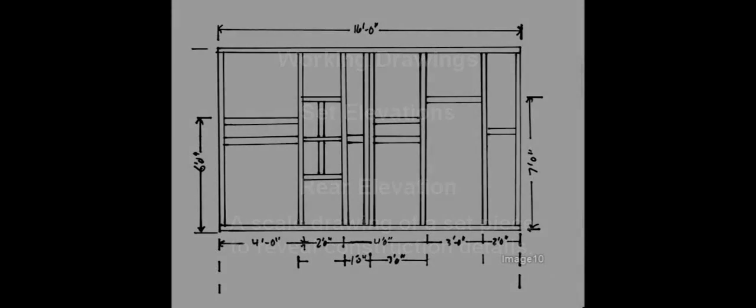Since the audience will, in most cases, never see the rear of a set piece, one must wonder why a designer would go to the trouble of generating a rear elevation. The purpose for the rear elevation is simply this: to reveal how a set piece will be constructed. While a front elevation reveals the appearance of a set piece and utilizes dimension lines to reveal where the set will be dressed, the rear elevation reveals the essential locations and techniques of construction.